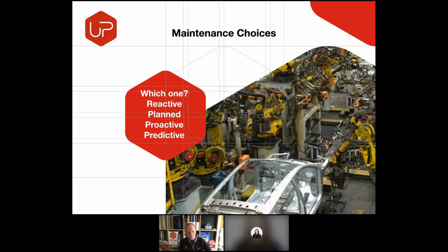There is another way we can look at things, and we can look at things kind of proactively. We can put some lubrication regimes in. We can make sure that our aligned components are checked on a regular basis, that they're still in alignment, they're not vibrating excessively, and we can use some predictive tools. And the first predictive tool you use is people. People is what makes prediction work for me. So if you can train your people to use their eyes and their ears, that's really the best place to start.